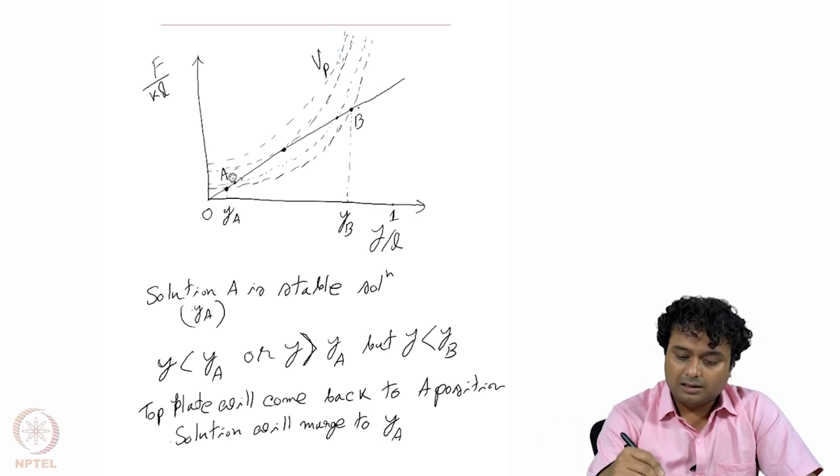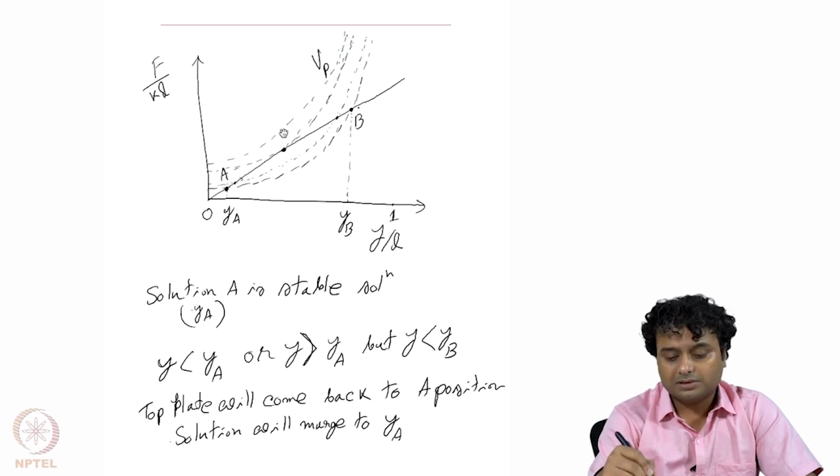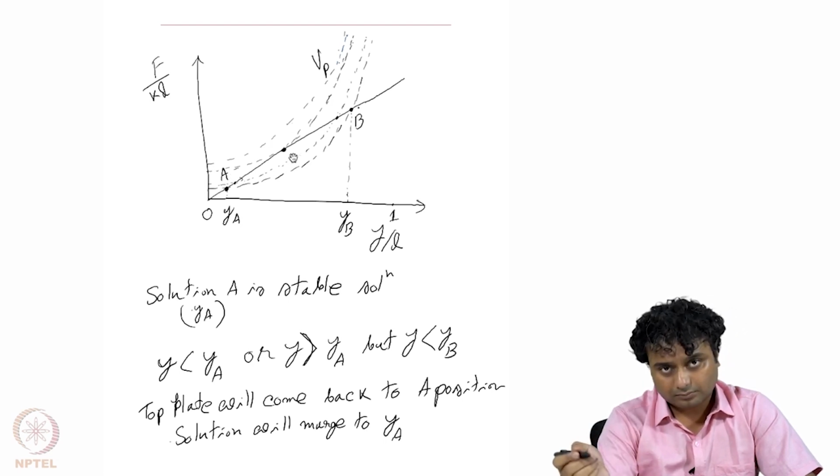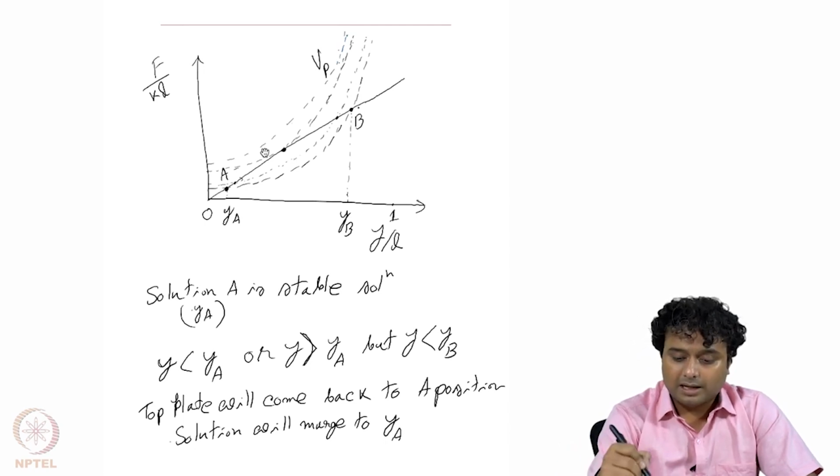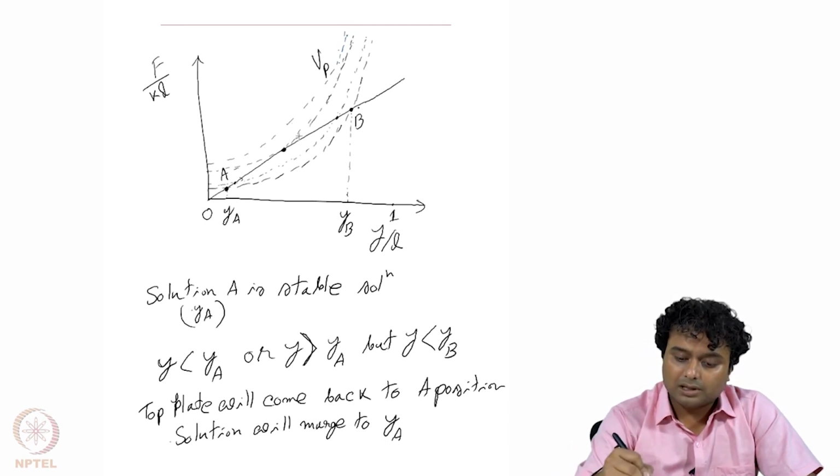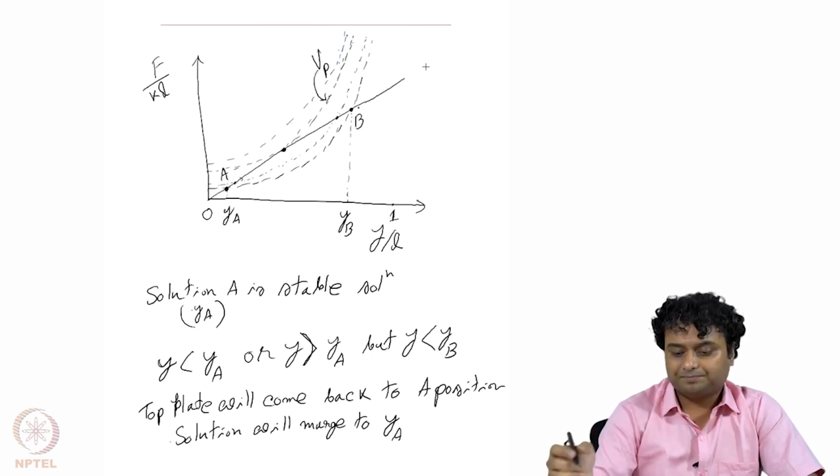Also we have seen that these different lines are for different voltages, and at some voltage where the electrostatic force just touches the mechanical force, at this point, this is called the pull in voltage. Above that, electrostatic attraction is always higher than the mechanical force, so there is no chance that the beam can be pulled back again. So this is called pull in voltage, Vp, and this is the graph for Vp where it is exactly touching the mechanical force.